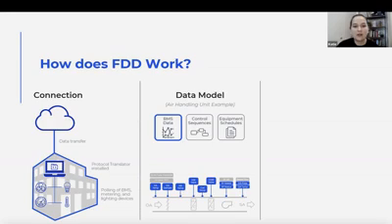And then your FDD provider will also input the control sequences. So what it would expect your system to do goes into your fault detection and diagnostics program. And so then it lives there real time, live, and it knows. The example that's given here is how your economizer works. What are your high limits, and how is it controlled?